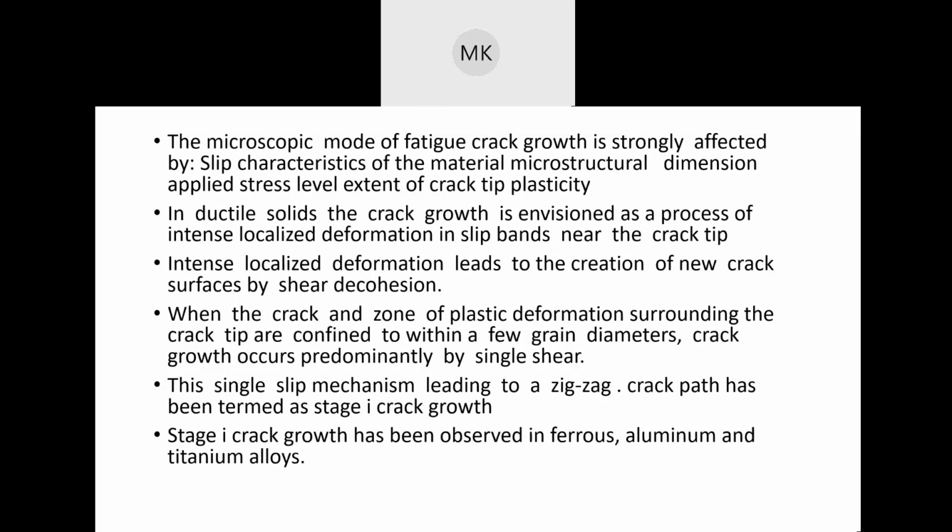The dislocations that were growing were maximum in that region. The other ones become non-dominant after a certain length. So intense localized deformations. That's the reason how when the plastic zone becomes bigger, there's a lot of localized deformation that happens, and that will generate your new crack that is growing from the plastic zone.